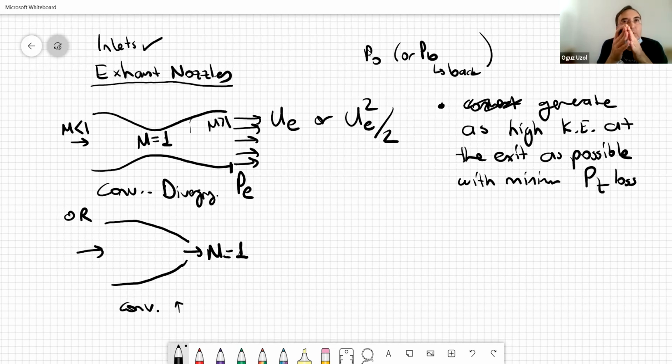However, when the jet becomes supersonic, nozzle does not know what the back pressure is. It has its own PE. And it may be bigger, it may be smaller than back pressure. Why doesn't it know what the back pressure is? Because that information, which is propagated by speed of sound, cannot reach the nozzle because nozzle is issuing faster than the speed of sound. We understand this point.